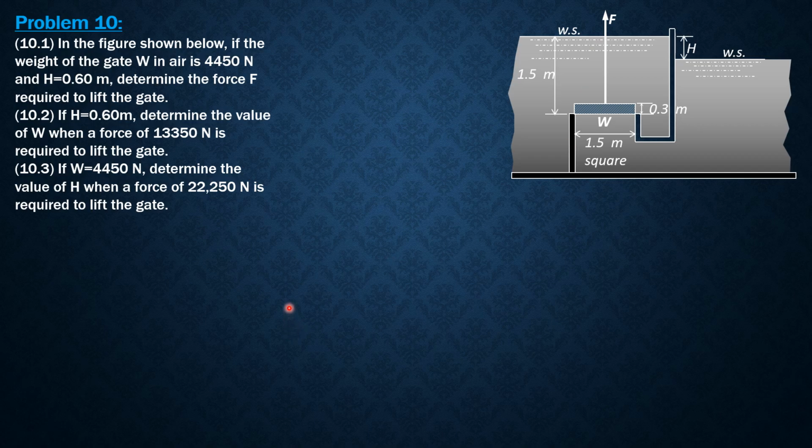In one particular problem, for the first, let's have the upper part subjected to a downward hydrostatic force, gamma bar H times area. The lower part is subjected to an upward force, gamma bar H times area. Then we have the weight also. So this is the free body diagram. F1 is due to the hydrostatic force of water, and it is gamma bar H area, where bar H is 1.5 minus 0.3 for F1.